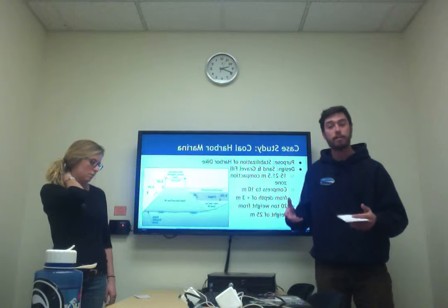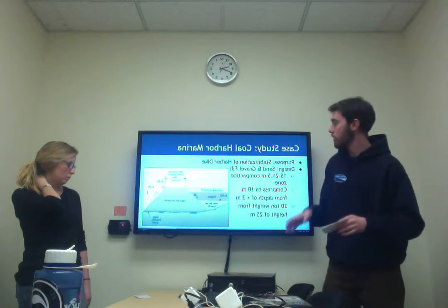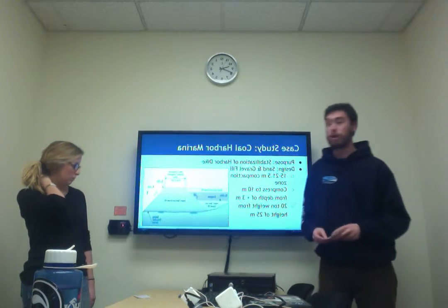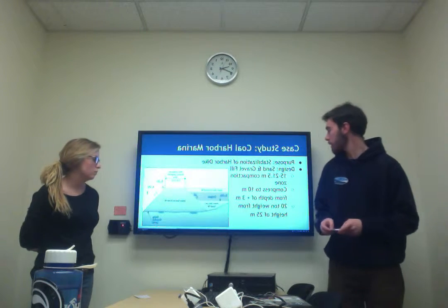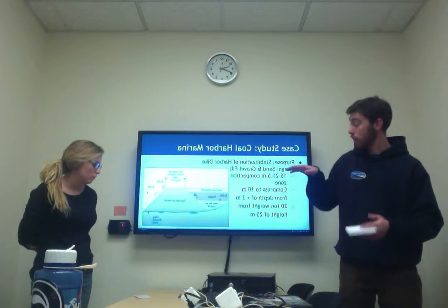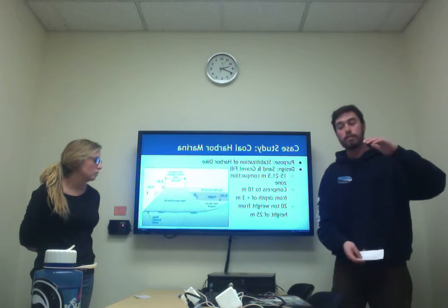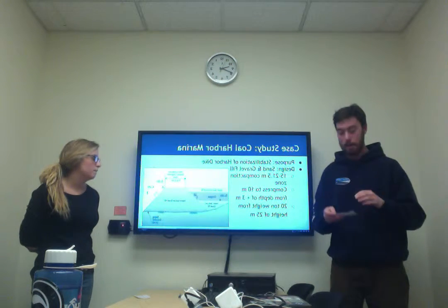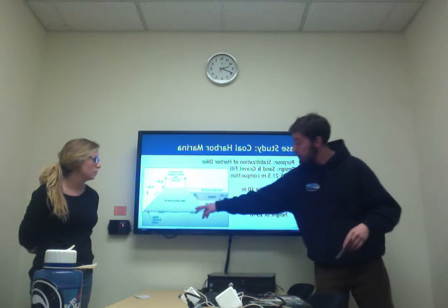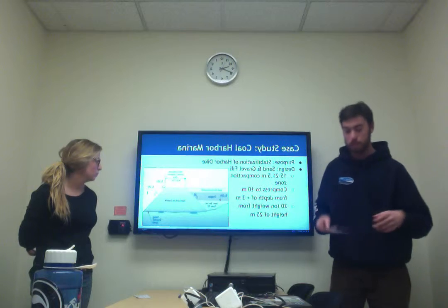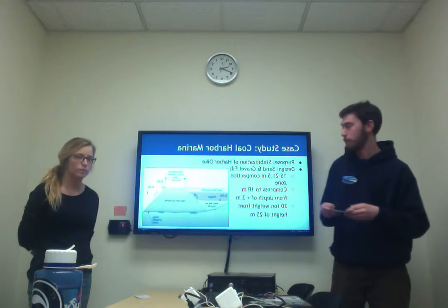So the design of the dike was that they had a compaction zone that was 1.5 to 21.5 meters wide. It varied depending on what the soil was right there. The column of soil that they added was 13 meters deep, and they were compressing it down to 10 meters. The material used for the import sand and gravel was under 75 millimeters, which is around 3 inches, not 3 feet.